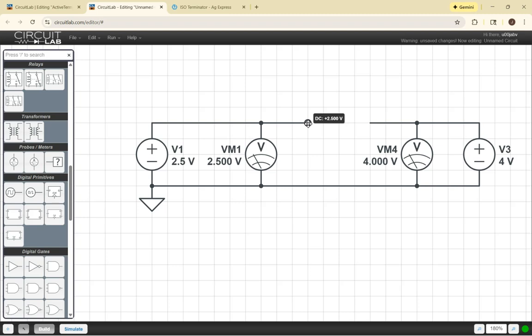What's going to happen is if you were using jumper cables to do that, something has to melt, something has to give up. We're not allowed to do that. We're going to flow a lot of current and we're going to make a lot of heat. So as long as I've got this resistor in place, it's okay for me to have what appears to be 2 different voltage sources in parallel. And they're not really in parallel because we have this resistor in place. So this allows us to have different voltage values measured on either side.